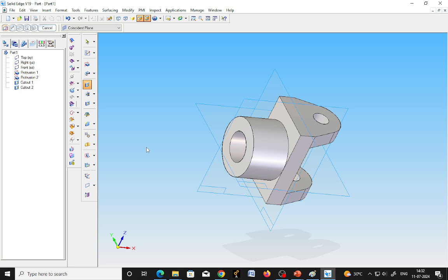Okay. What remains now? Keyway. Now if you just observe the keyway, they have not specified any dimensions. So it is not a taper keyway, it is a normal parallel keyway. So you can just go for half thickness in a shaft and half thickness in a bore. They have provided the keyway, it is 8 into 3.5 mm. Okay, it is 8 into 3.5 mm.